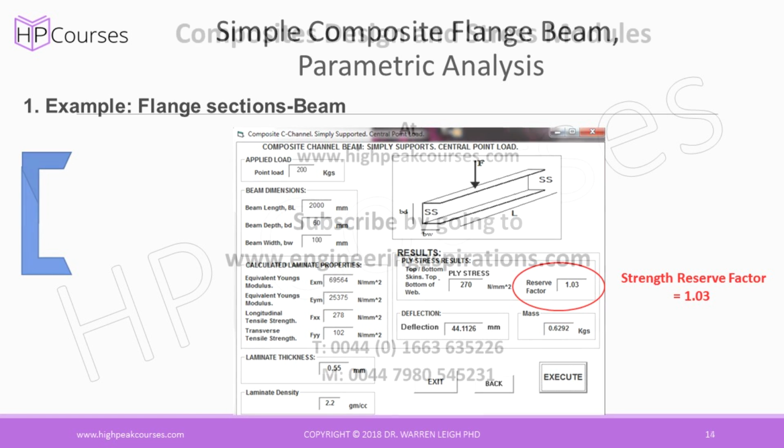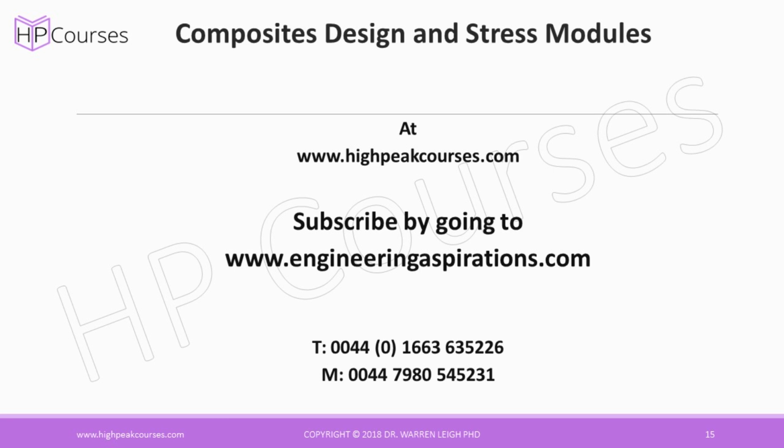To summarise, what I have explained in this lecture 4 is the effect on composite mechanical properties by the introduction of angled plies into a composite laminate design. We have looked at two different material type composite laminates. The first was of 2 layers of unidirectional glass fibre. The equivalent Young's modulus and strength in membrane remain the same in this laminate architecture design no matter how many layers of unidirectional glass fibre were stacked on top of each other. Only the thickness of the composite changed.